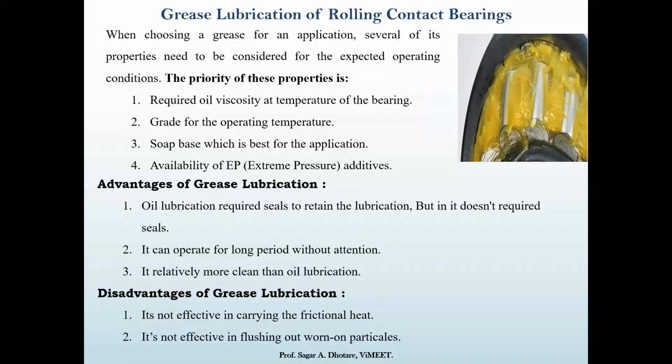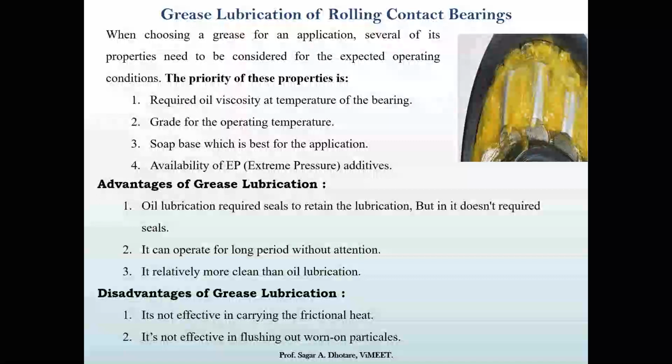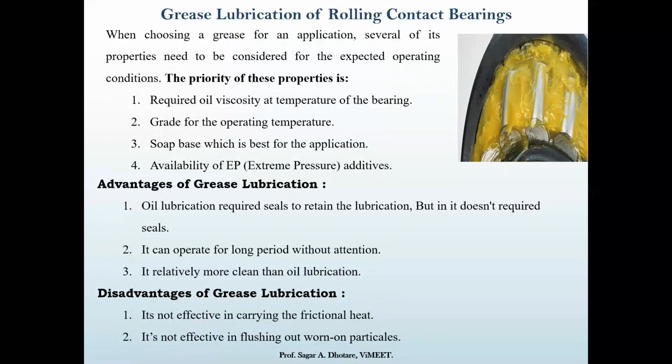But the disadvantages of grease are, it is not effective in carrying away the frictional heat. In that condition where temperature plays an important role, if the temperature is high, we should not use, or we never use, grease as a lubricant.